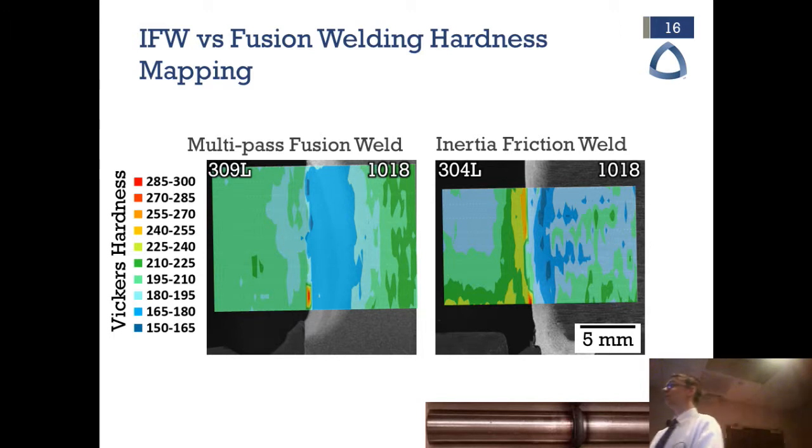So you're mixing and matching specification standards, metal standards? That's incorrect. AISI classification 1018, AISI 304 stainless steel, those are all AISI. But ASTM has their own classification. So no, he is not mixing those.